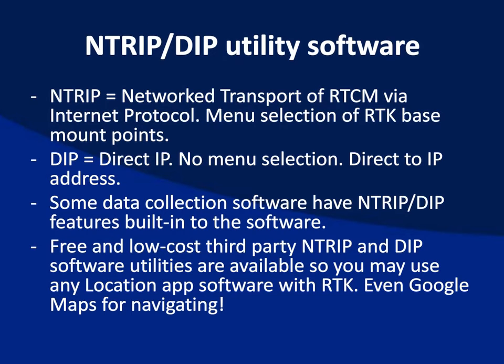Typically when you log on to an RTK network, one of the formats they output invariably is RTCM3, and basically it's the same as ASCII, if you remember the old DOS world. ASCII was a generic table, a generic format everybody used and understood. RTCM is the same thing. It's a vendor-independent format for using RTK, and so virtually any RTK receiver out there can read this format.